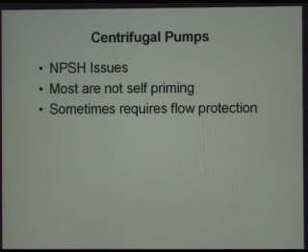This has a similar situation in that instead of having a nice laminar flow coming off of the impeller vanes, if you get down too far in flow, it just recirculates inside the impeller. You have very little head rise, but you generate a tremendous amount of heat and a tremendous amount of vibration inside the pump. And if you operate there for very long, you end up burning your seals out.